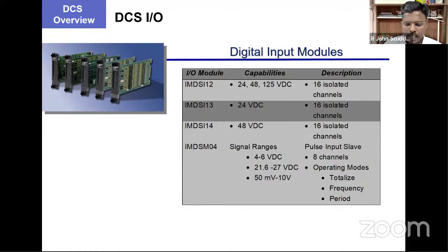So these are all different kinds of modules or electronic cards, which will be receiving each input from the field. DCS modules are mostly having 16 channels. These black color modules which I have shown you in the picture all have different channels. Each channel can have one parameter.